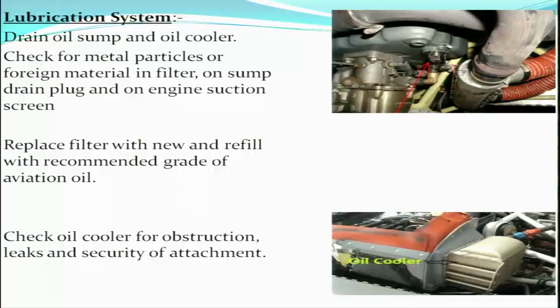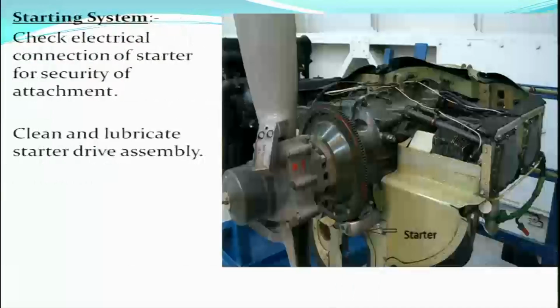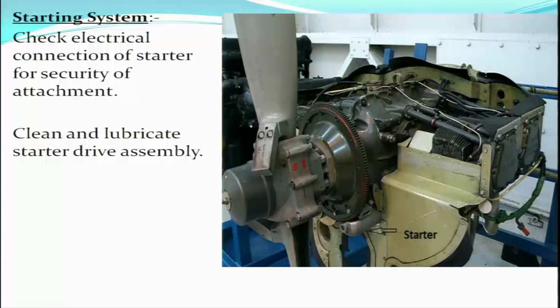Check oil cooler for obstructions, leaks and security of attachment. In the figure you can see this is your oil cooler. This oil cooler is to be checked for obstructions, leaks and security of attachment. Next comes your starting system.